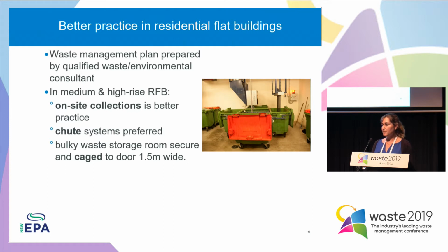In terms of bulky waste, there's an emphasis in the document that we try and encourage bulky waste storage rooms to be built in residential flat buildings, and I've given them some guidance there around what they should look like and how big they should be. For just simple things like not using a standard door width, having a door width that's 1.5 metres wide, so that you can get a mattress or a larger item in, having a caged front so that people can look into the room and not have fear of something falling on them. They can see what obstacles are inside that room, because I'm sure they can get quite overwhelming with a whole range of waste in there.